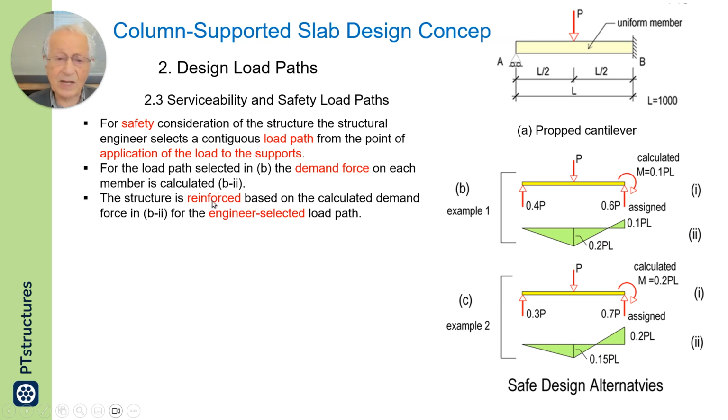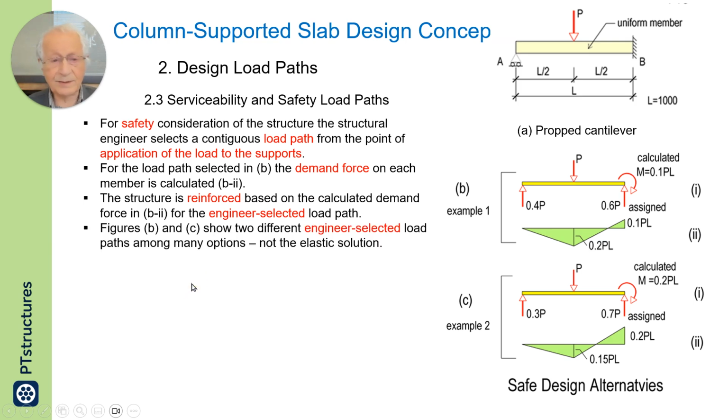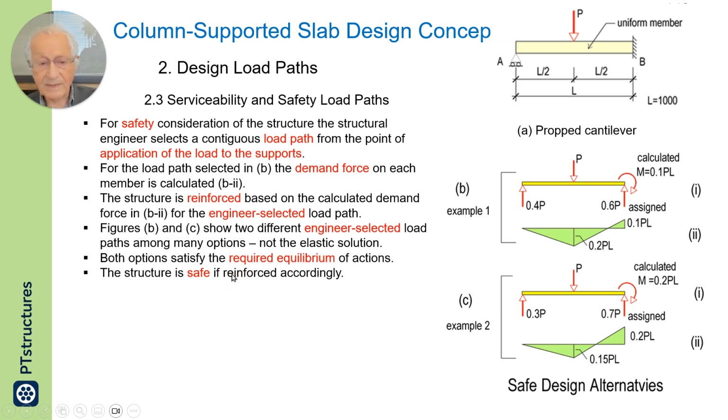The structure is reinforced based on the calculated demand selected by the engineer. Figures B and C show two different engineer-selected load paths among the many options. Both options satisfy the required equilibrium of actions. The structure is safe, is reinforced accordingly.